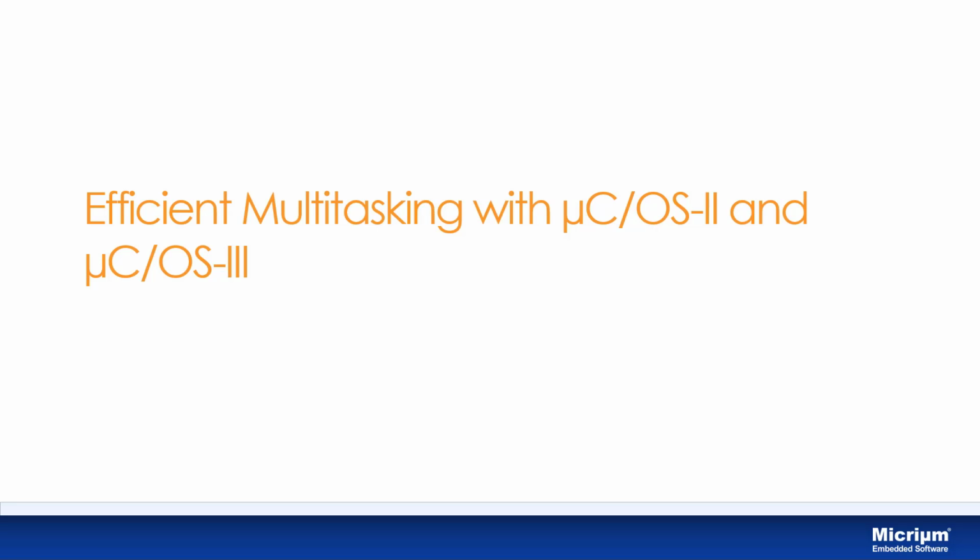However, there's certainly no guarantee of efficiency gains in the move from single-task to multitask application code. To realize their CPU's potential, developers must select a kernel that is itself efficient, and they must know how to configure the kernel and write their application code so that it too will use CPU resources efficiently. In this section of slides, we'll see that MicroCOS 2 and MicroCOS 3 are indeed highly efficient kernels in terms of both CPU overhead and memory footprint.